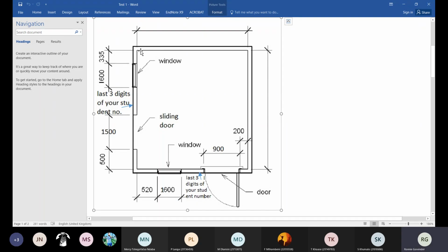Then the next item was your DPM. DPM is fairly straightforward. You would have used the total length times the total breadth, right? That you calculate. I said we take the total length times the total breadth just to allow for that little bit of wastage, right? That would have given us square meters. Then cement bricks, all you had to do was the same value. I told you to use the same thing for cement bricks. There were no internal walls here. You didn't have to calculate anything. It would have been the same value for the cement bricks.